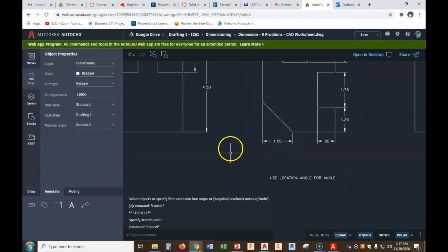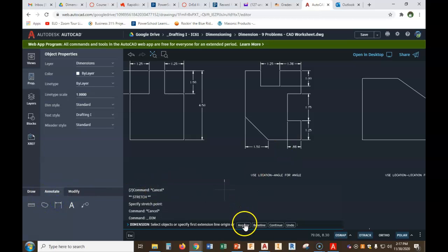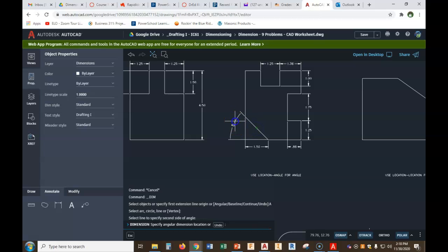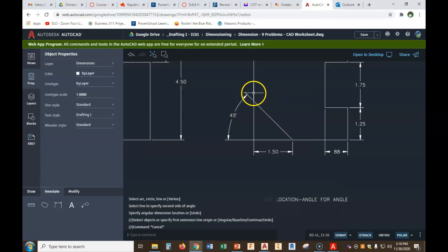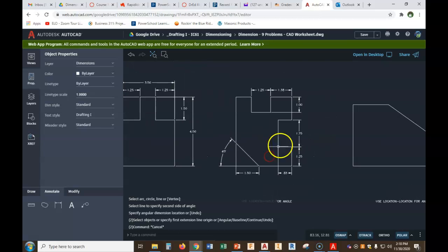All right, now, it said to use angle. So, now watch what I do this time. It's the first time we've done this because all we've done so far is what's called linear dimensions, left to right or top to bottom. Okay? Click again. But now look, click on angular down here. Okay? Now, we want it from the horizontal to the angle itself, and now drag out. Now look, still about the same spacing, about 3/8 right there, from the end of the arrowhead to the line. So that's pretty good right there, 45. There we go. So now, what's the only thing we got left?